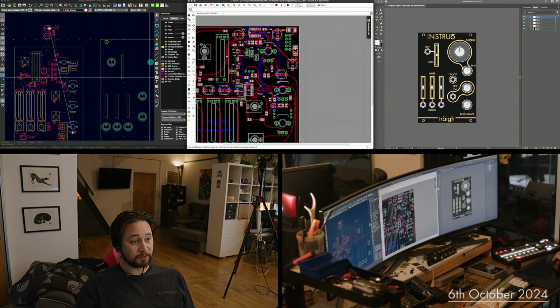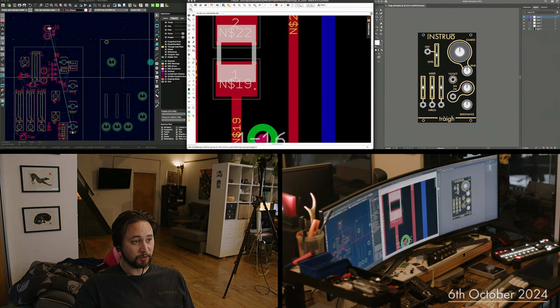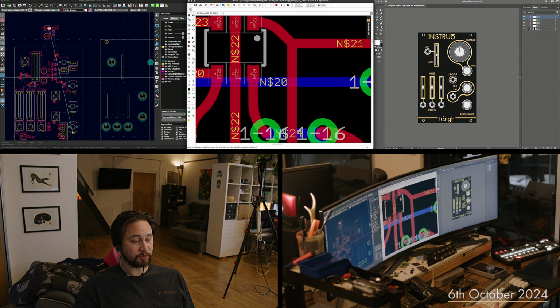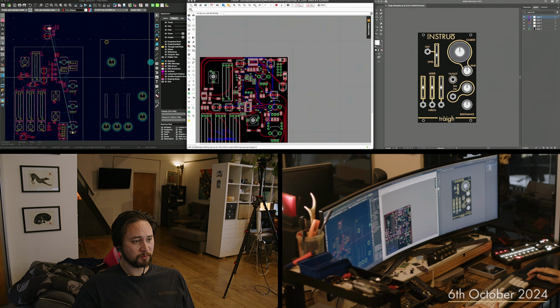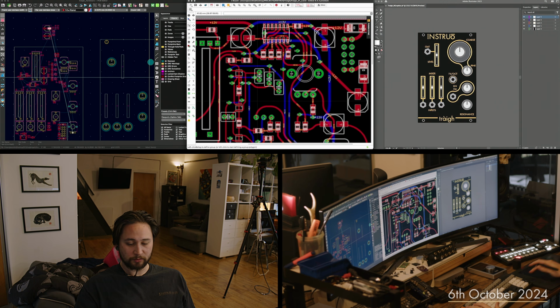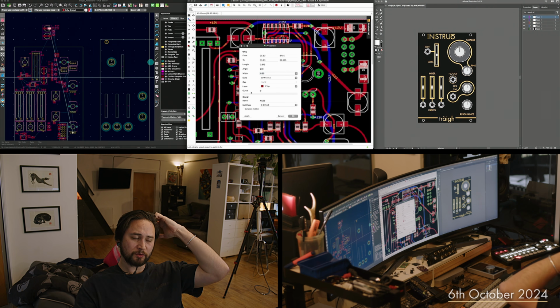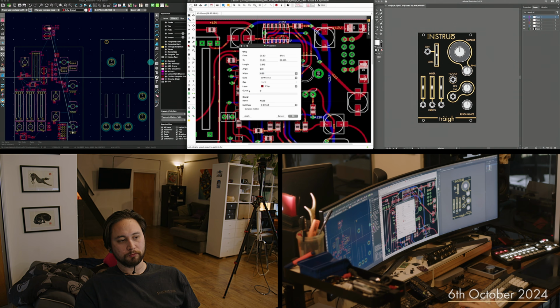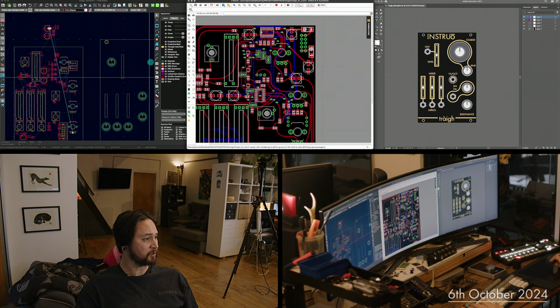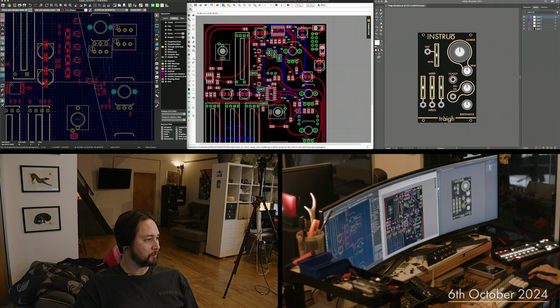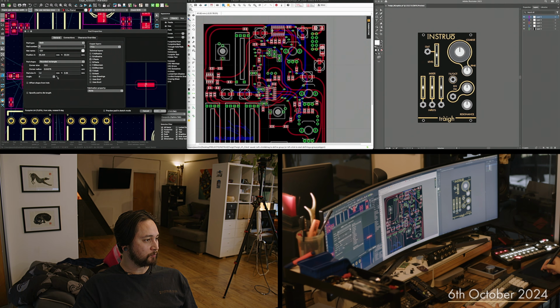These are thick traces, so I think I'll maybe try and keep them the same length. What is that as a... Oh, it's only 0.35. It looks thicker than it is, strangely. And 0.35 is pretty chunky. I guess the limit will be the pads themselves.